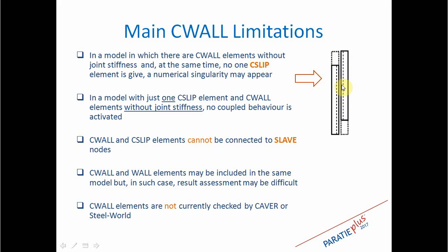Normally this problem is not highlighted. And according to this, if you don't consider slippage along a wall and simply restrain one level, the coupled behavior is not activated. So the two walls act as separate walls. And moreover, such elements cannot be connected to slave nodes.